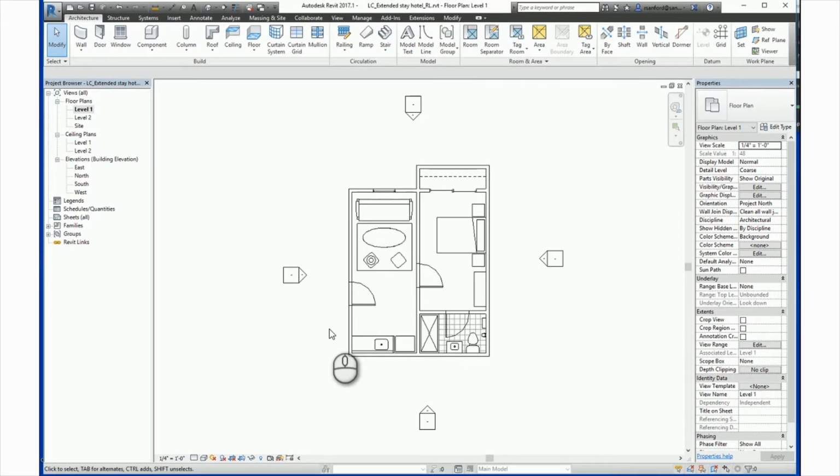Since hosted components must be placed on a host, it would be necessary to provide such a host before a fixture requiring one can be placed in a project. For example, to place a ceiling light fixture for an interior room scene, a ceiling must be created if none already exists.